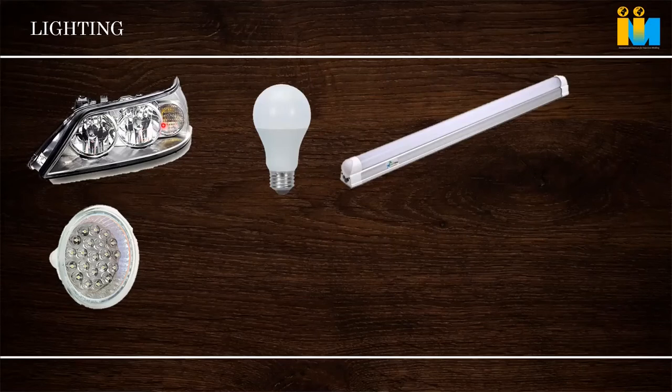The basic properties and molecules remain the same, and it has very good light transmittance, like 90% or 92% of light. So whenever we are selecting electrical lighting grades, the optical property in the data sheet will be added for that type of grade. We have to see maximum 90; PMMA goes up to 92, 92.5. That is the maximum available, 92% transmittance. Above that, if we require more, we have to go for glass only. Polycarbonate has 90% and 91%. Optical quality has 91%.